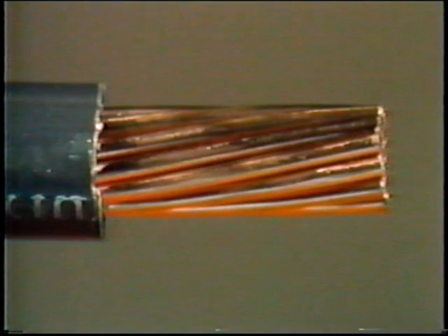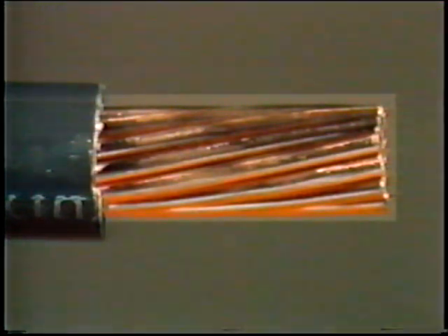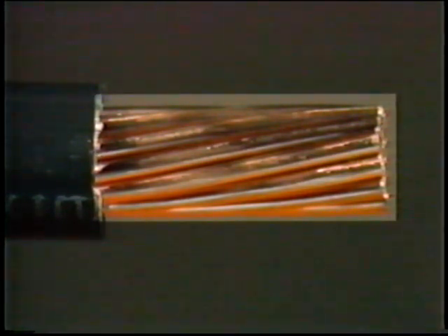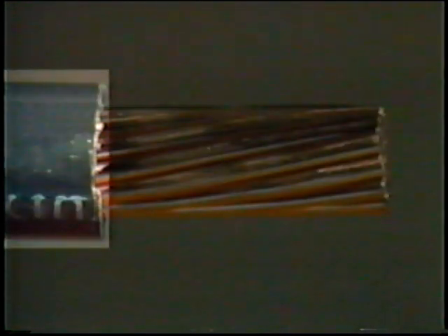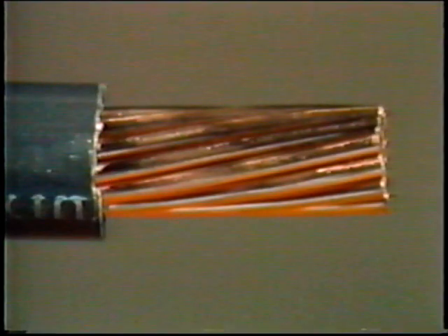Cables and conductors are classified according to two things. They're the size of the metal wire in the conductor and the type of insulation surrounding the metal wire. Cables and conductors are rated for two things as well. They're rated for the current carrying capacity of the metal in the conductor and the value of the voltage that the insulation surrounding the metal wire can withstand. Let's go into the subject of classification in a little more detail, and then we'll cover ratings.